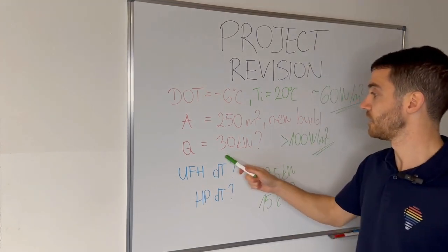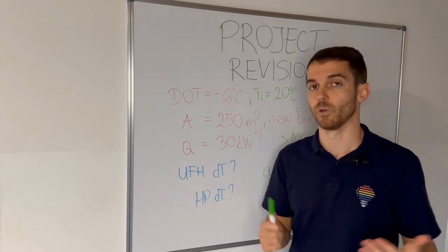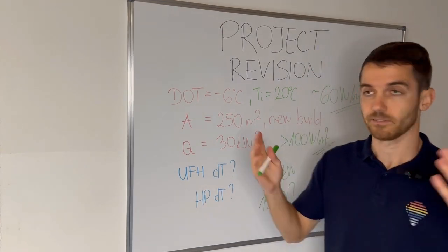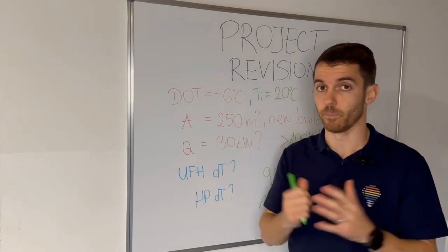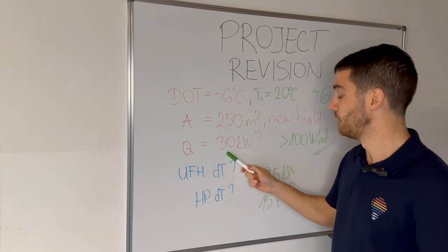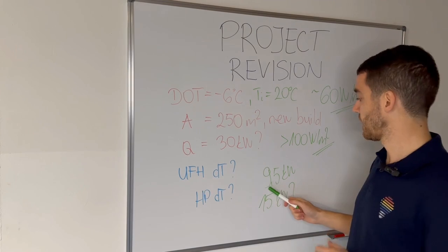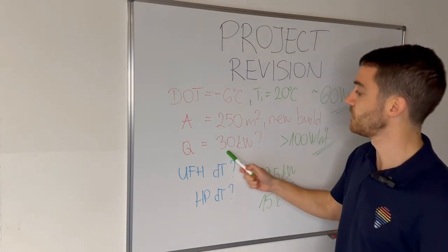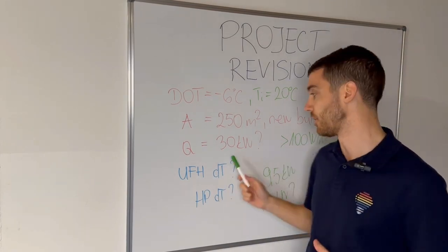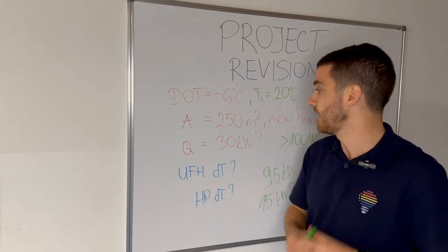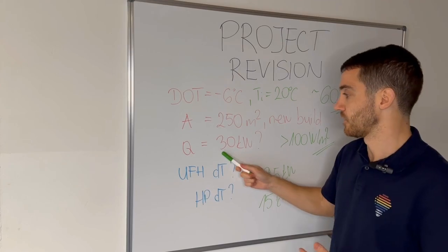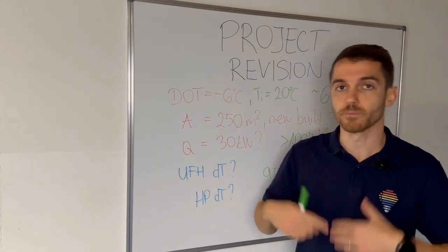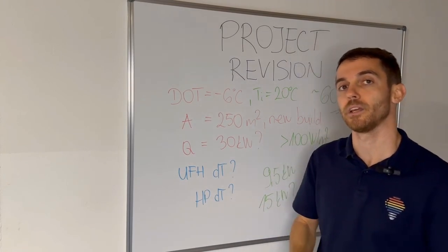What is the main thing here? For this 30 kilowatt unit, minimum modulation is around, let's say, 7, 8 or 9 kilowatt at some point. At minimum, it's more than this house is losing at design outdoor temperature. So this unit will always work on and off, always, and minimum electrical consumption will be really high, because with 10 kilowatt you will spend a really high amount of electricity.